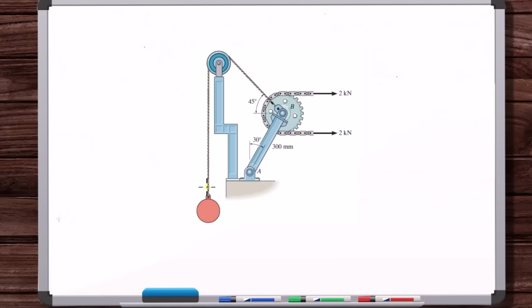You think of the fact that this rope could swing back and forth as a degree of freedom of the rope, just like this is a degree of freedom here. It's only non-rigid if you put a spring here, so if this could deform. So with that in mind, you can take a snapshot of the system at any moment in time. If it's still, then you know it's still. When you take the snapshot, you just have to specify what the acceleration of the system is.